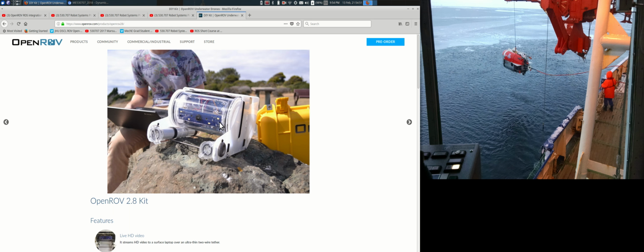And they took the crappy camera that comes with the robot and replaced it temporarily with a decent machine vision camera. And this robot runs on a BeagleBone Black, so they put in a second BeagleBone Black just for image processing. And both of the BeagleBones in this pressure housing could talk Ethernet up the power line to the surface. There's a power over Ethernet 2-wire interface.